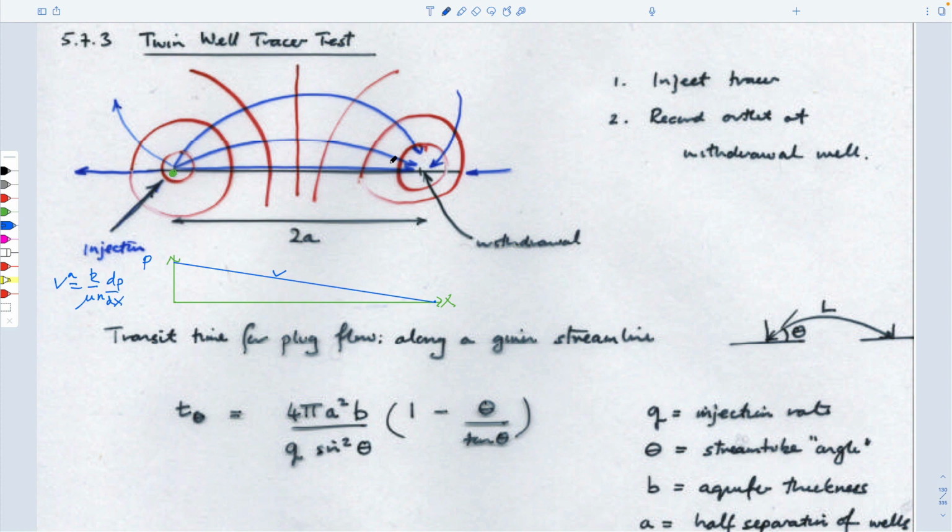And so if you think about the streamlines, this is basically a flow net that would describe that. The only requirements of a flow net are that each of these cells, as you remember, must be roughly equidimensional. The width and the length of the cells must be roughly the same. And if it satisfies that requirement, we could exactly calculate what the flow is in this, right? The volumetric flow in this would be equal to the number of stream channels, over the number of drops, times the hydraulic conductivity times the head drop.